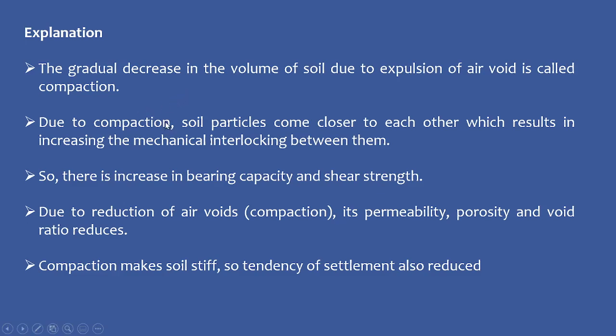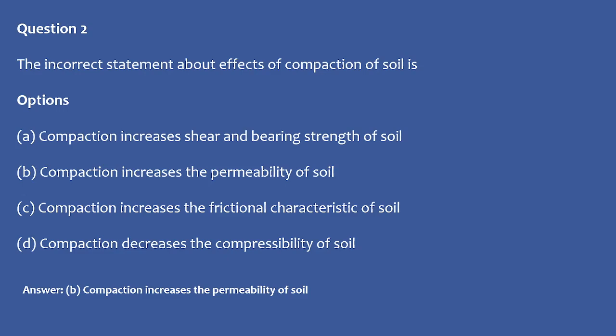Also, after the compaction, the soil particles will come close to each other, and there will be some interlocking between them due to that densification, which will increase the bearing capacity and the shear strength. And since there is a reduction in the air voids, we can clearly observe that there will be a decrease in the permeability and the porosity, and in the answer it was given as the increase in the permeability of the soil,